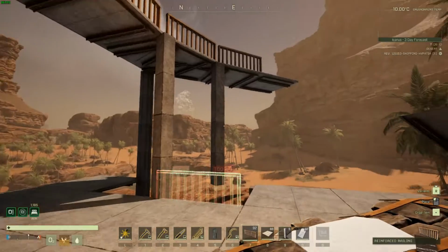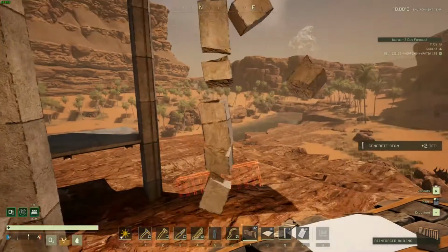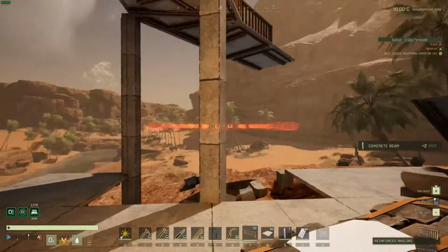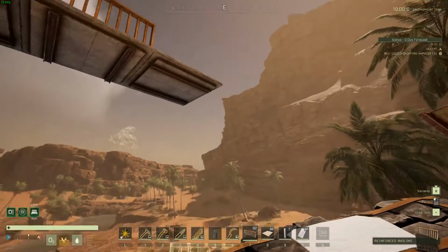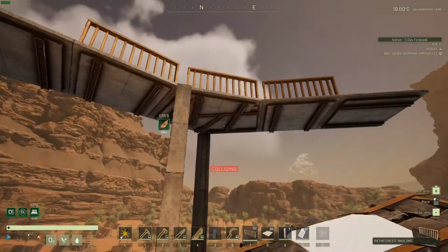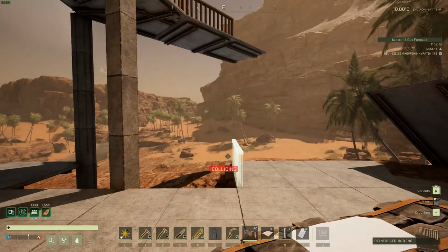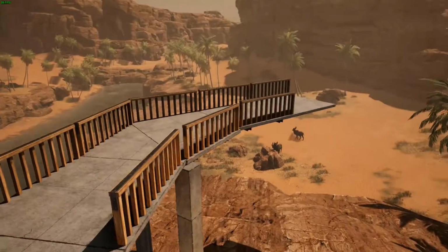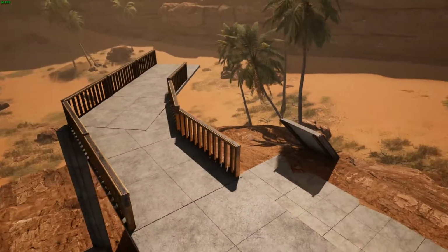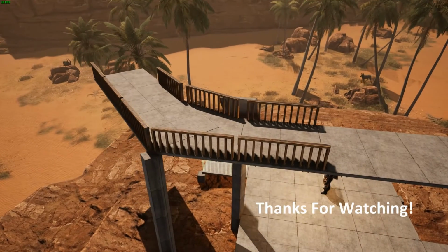And of course we don't need this one here anymore as a guide. That was just a guide beam right here. And that's what you're left with. Now as you go further out, you're obviously going to need to provide some more supports, but at least you've got this part looking half decent. So I hope that was useful in some sort, and you picked up a tip there, and that's how you would do a little bit of an angle transition for a raised platform.